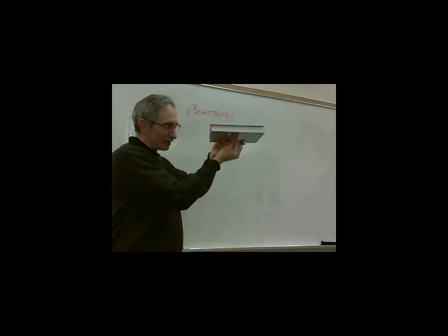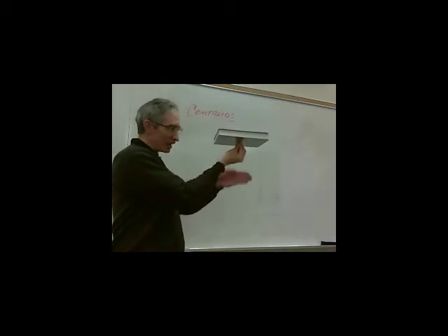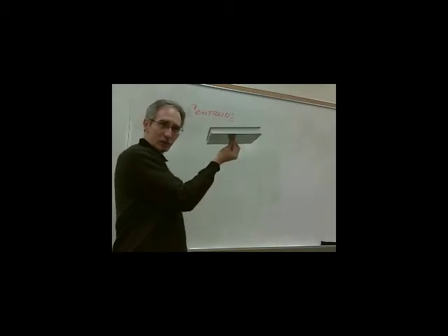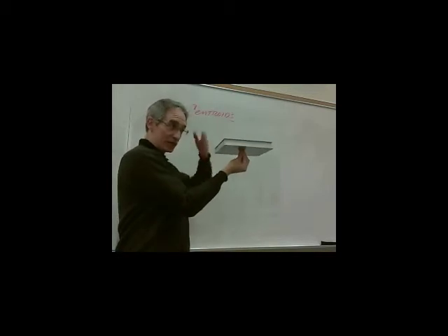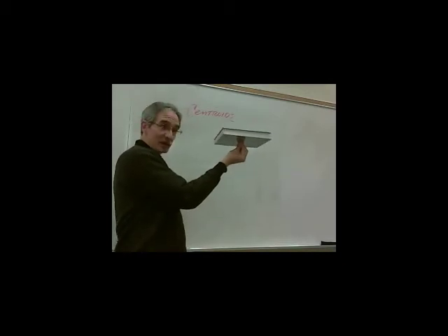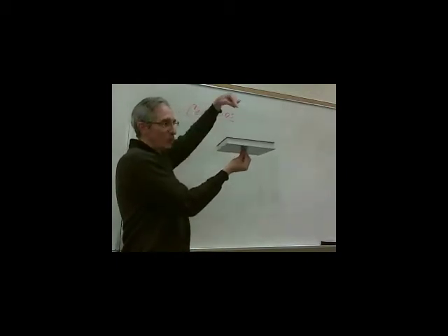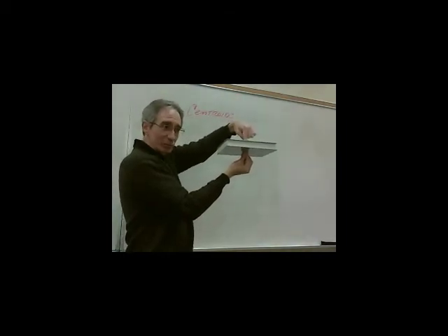If you could find the point in that book where all the weight on this side perfectly balances the weight on that side, as well as on this axis, this side, and this side, you can find that balancing point in there. That would be the center of gravity. Now what the center of gravity would also tell us is that's where the resultant weight would be acting.